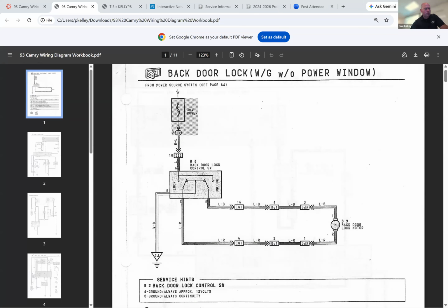However, and this is why I spend so much time explaining, you got to know what you are trying to test. So if I were to start this off with saying the customer states their door locks are inop, how would you verify that? Yeah, press the lock switch. And if you press the lock switch and it doesn't do anything, you're like, oh, your door locks don't work. What would you sell the customer? We don't know yet. Make sense?